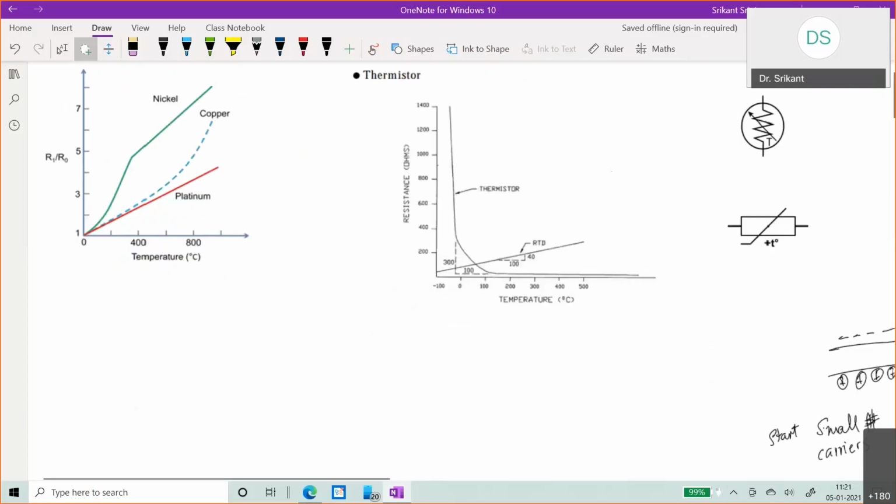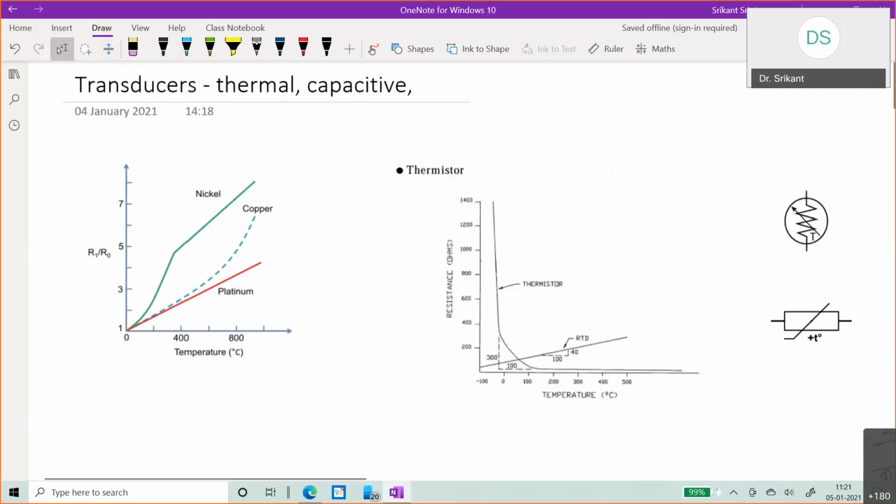So if you look at the case of metals, metals usually have a high number of carriers, right? We know metals are conductive by nature, all the most popular metals. Copper has very high conductivity. It's one of the most conductive metals, silver and so forth. So if you were to take a curve of temperature versus resistance, you actually find in metals that the resistance increases with temperature because there are already a huge number of carriers, and therefore the temperature keeps increasing.